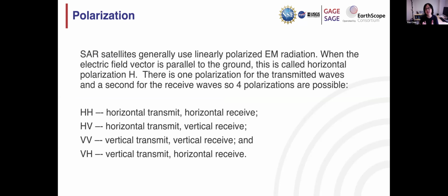That's the typical idea of Stripmap processing. The radar holds the antenna pointing in a particular direction. It sends out pulses and receives echoes from near range to far range. As it moves forward, it keeps sending out pulses at a fixed small time interval. That's what we call the PRF, or pulse repetition frequency.